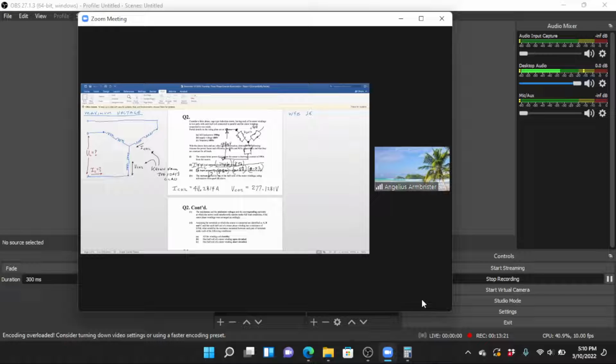In other words, where does this current here come from? This comes from right here, from the phase. That's I phase. And where does I phase come from? I phase comes from right here. That's I line. So the line current goes straight down into the coil, so the three of them are the same. So the answer for I line is 411.2814 amps. That's the answer for that.